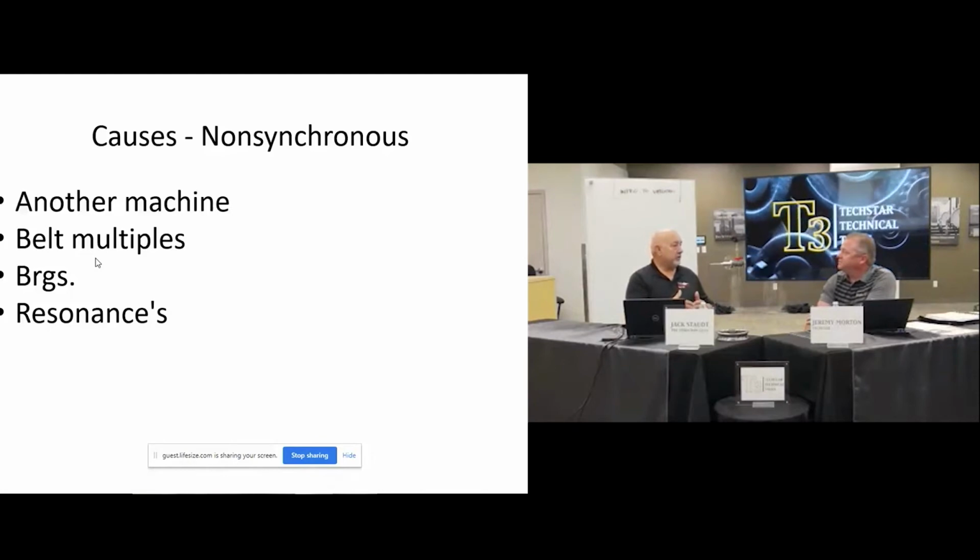There's also some places where you can go to. Most of them are transducer companies that have some type of calculating software on their website that you can use, where you can input all the bearing information. If you look at all the physical data of the bearing and plug it in, it gives you your natural frequencies. Oh, nice. Inner race and outer race too. Yeah. So it's a lot of work doing it that way. It's a whole lot better just to call out, hey, what's the outer race? Just get it that way.